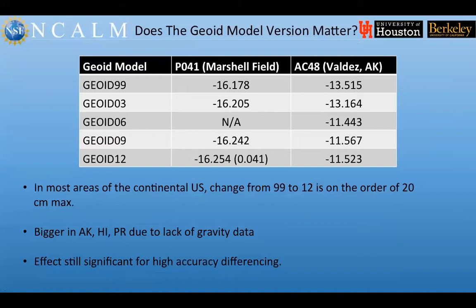If we look at the one at Marshall Field here, with 99 we go from 16.178 to maybe 16.254. So 8 centimeters different. It's kind of debatable whether or not that would be in the noise of the LiDAR data. Not much of a change.